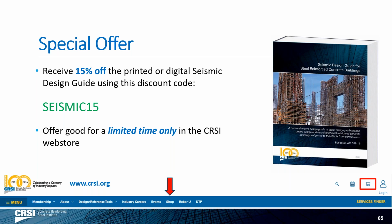We're still limited to grade 60 reinforcement. Reason being is basically for crack control. So that's why you're going to see the 60 KSI in your typical, other than high seismic situation or special seismic situation. That is the case.